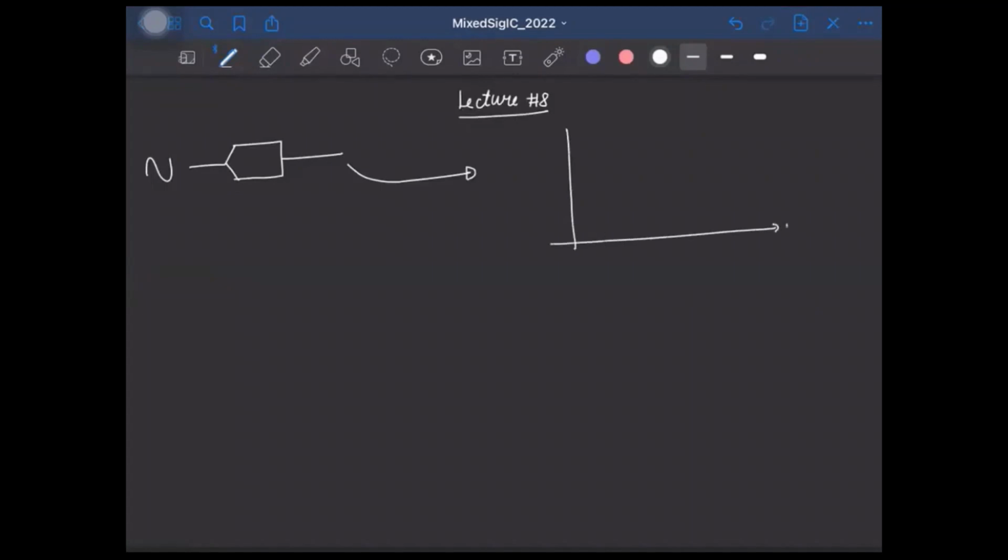So let's say this is the bin number K. We will have one impulse corresponding to the input sinusoidal frequency. And due to the circuit implementation, we'll also have non-linearity. So we'll have harmonics of this input signal, right? And the other bins will be filled by the noise. Okay. And this noise will be both due to the quantization noise and the random circuit noise.